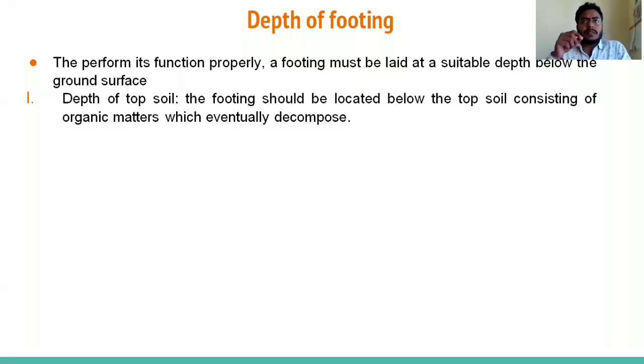Basically we are designing footing. We are selecting the dimensions of the footing, like depth, width, length, according to the bearing capacity of soil, and you have designed that footing. Suppose after some time, that bearing capacity of soil is reduced by some other factor, like I mentioned these factors. So what will happen? The design would fail. Structure can fail, right? You can get the excess settlement. You can get the differential settlement.